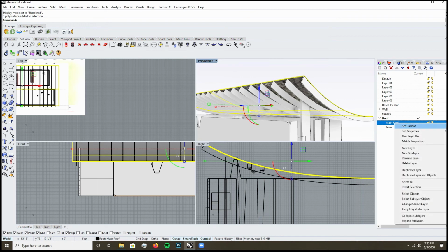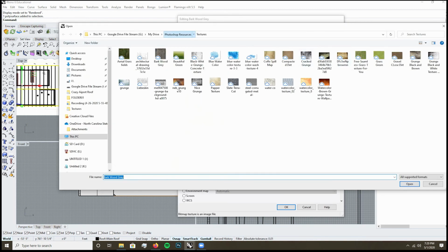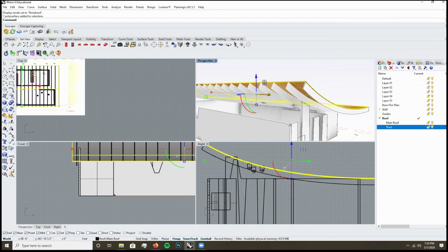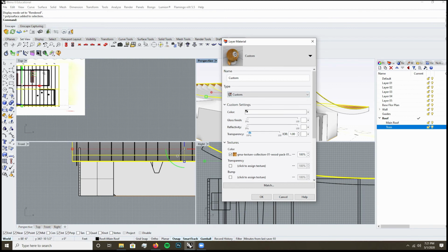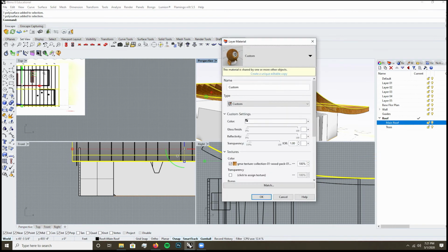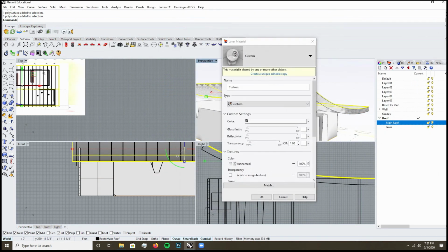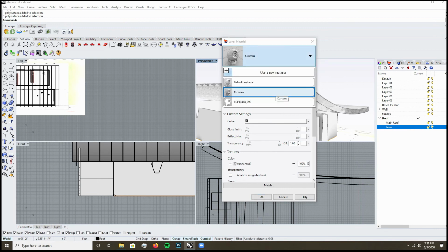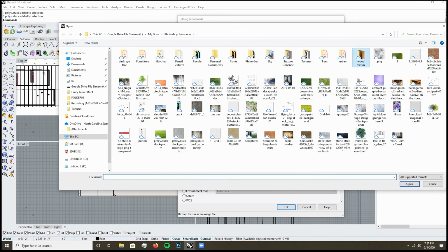That showed up very pixelated. So then you can come back here. Let's use a different material. Let's go to our wood textures and select a wood roof. Or let's say we wanted wood trusses, set properties, materials. Use that for wood. Give it a little transparency. And then come here and set our main roof properties to, let's give it a cool texture, a fun texture. Maybe some, oh, I didn't use new material. You have to press new material, then come in here. Truss. No, set it to the wood texture.